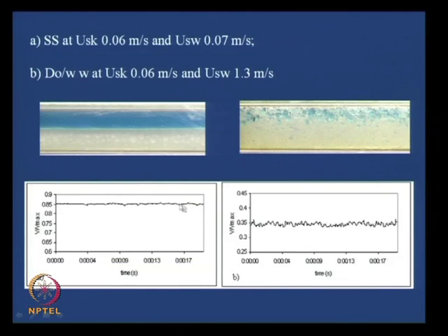Not only that, if you observe the signals, we find that when the interface was smooth, we obtained an almost straight line signal. On the other hand, when there were bubbles, each particular bubble surface or droplet surface behaved as a reflecting surface. They were reflecting the light, isn't it? So, therefore, the undulations were much more for dispersed flow. So, the two things were important in our case.